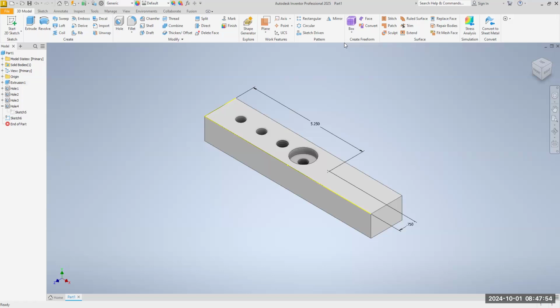What we're going to do here, spot face is a little bit different than a counterbore. Counterbore is you want to basically recess the head of the bolt so it's not noticeable or it's below the surface. Spot face is you just want to smooth the surface so that you can properly seat the head of the screw.